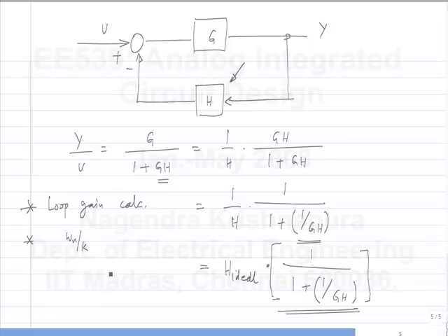So what we did was to try and make an amplifier of gain K. We realized that we can make it by sensing the difference between V0 by K and the input and driving an integrator using it. We also analyzed it in time and frequency domains. In the time domain, we see that asymptotically the output reaches the input if the input is DC. In the frequency domain, we see that for low frequencies, the output will be K times the input, and as the frequencies increase, it will start deviating from that. We also calculated some things like gain and the product of gain and bandwidth being constant and so on. So the next thing we'll do is to see the loop gain.